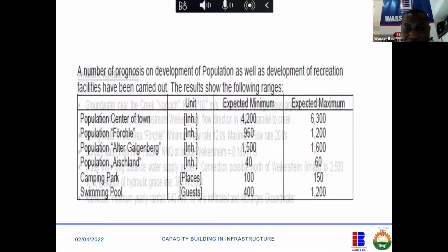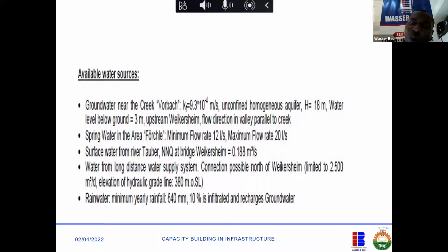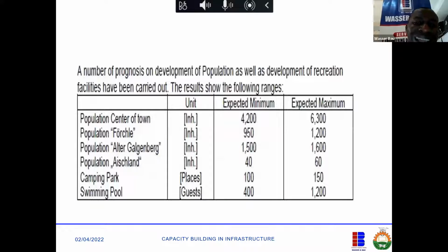So I've said two things. You have done your topography, determined the highest point, the lowest point, explained the topography, explained the area. You've looked at your water source, you've done your testing, you've seen the one that is best, you've developed the method for treatment. The next thing is you now start to project the population. You put them into phases or catchments so that you know how to pipe or how to distribute the water.